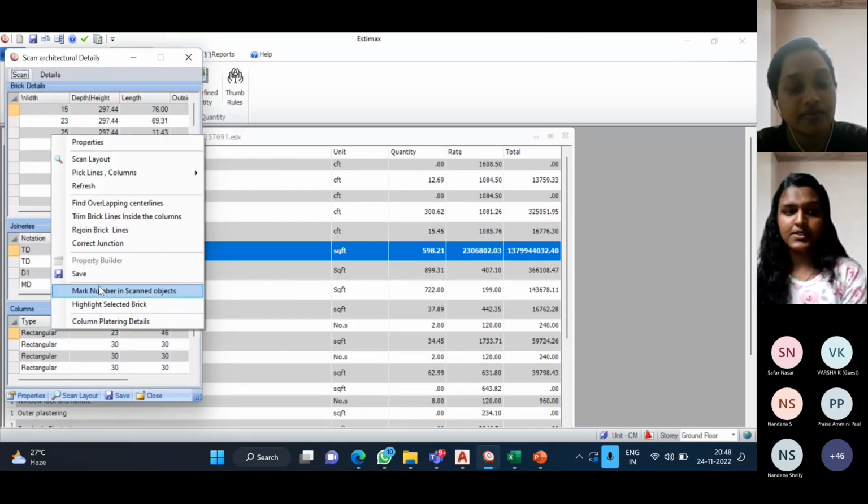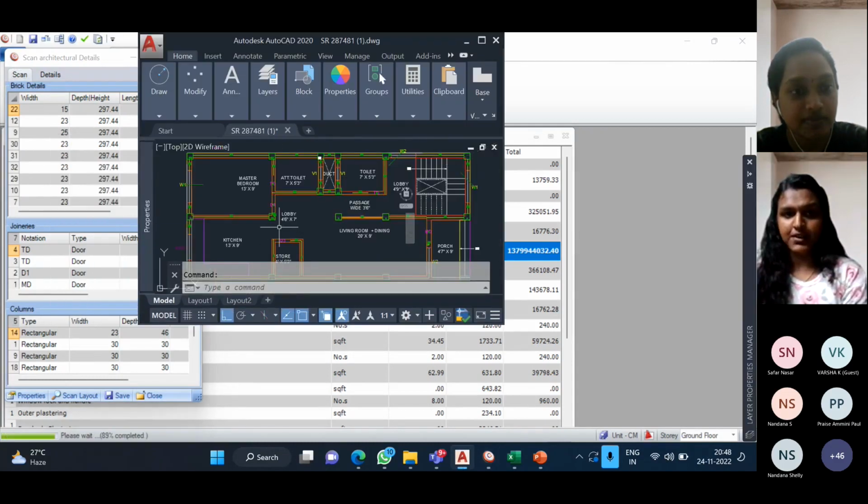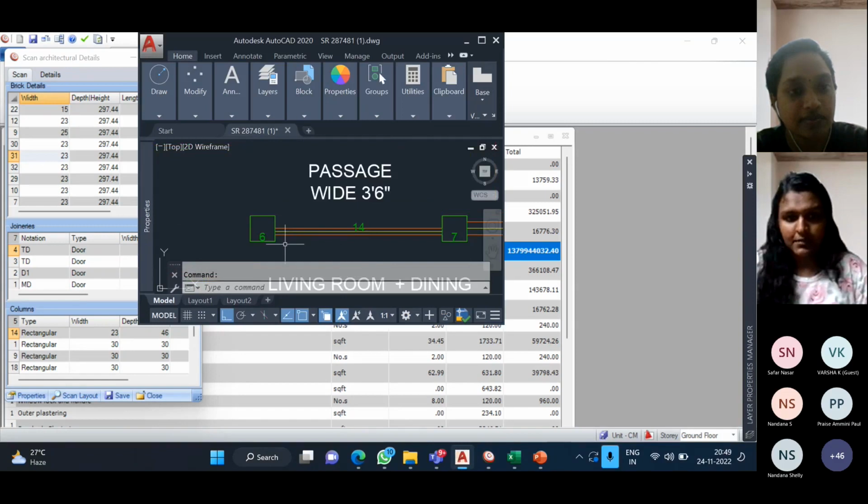The reason why we are providing the centerline numbering is that it will detect that particular component. That is, if for the project we want to edit the wall thickness or the wall height, we can automatically get into that part. When we click alt plus any number, this is the centerline number.